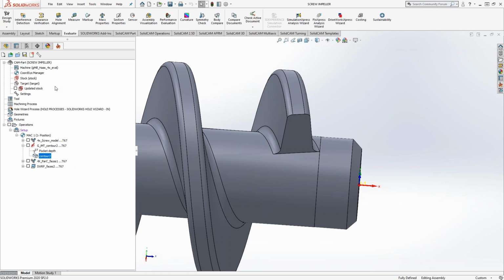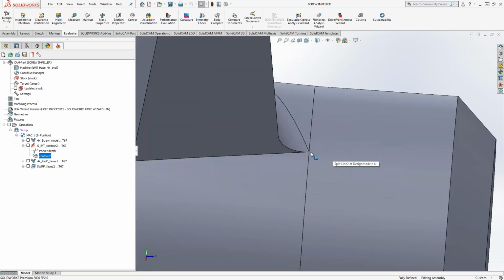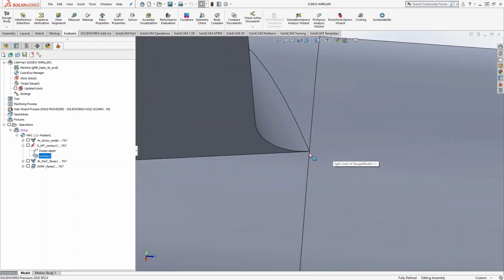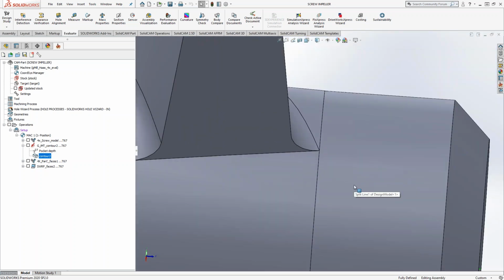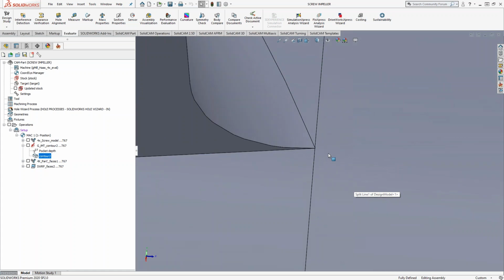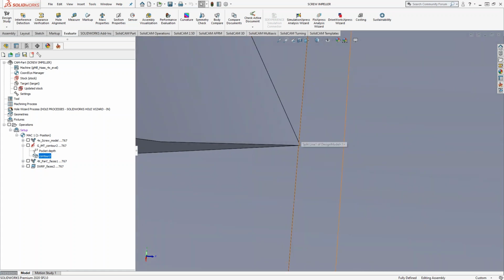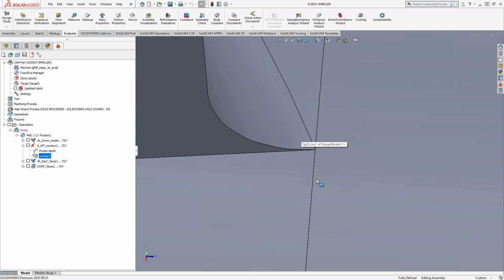The use of that is to get that edge. I had to do it a little bit past this point here, because if this was a continuous circle, then it wouldn't count as the wrapped edge of the pocket. So it's just a little bit past that tip there, so I get a discontinuation there. That acts like the edge of a pocket.